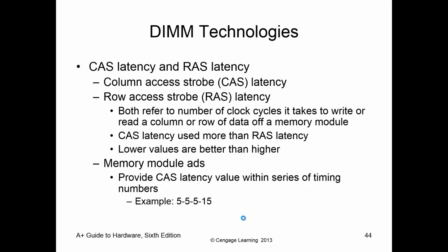And we measure this in 2 ways. Column access, or CAS, or row access, which is RAS. And this is the delay going between the columns and our rows. Now, how we actually verify the speed of our memory is we look at our CAS, our column access.